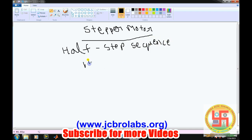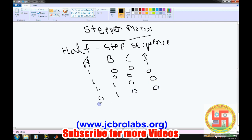So in this half step sequence there will be a total of 8 combinations by which we can rotate our stepper motor, and by one step our stepper motor will rotate by half an angle. So it is 1001, then 1000, then 1100, then 0100, and then 0110, then 0010, then 0011, and last 0001.